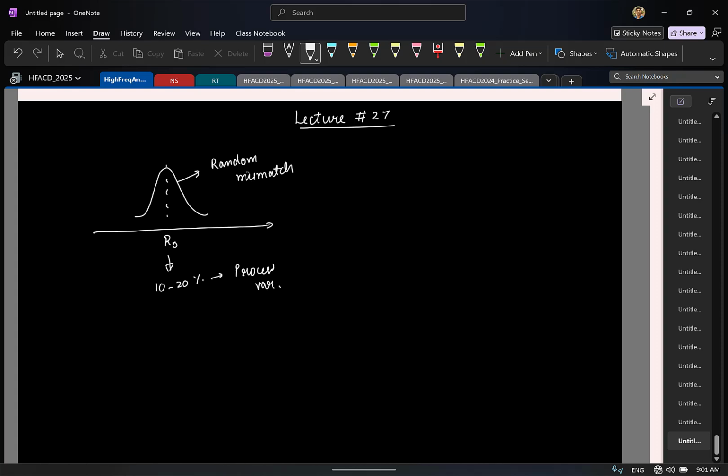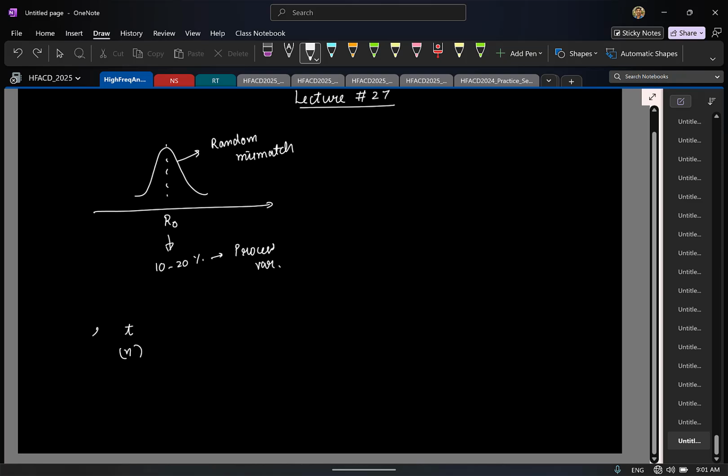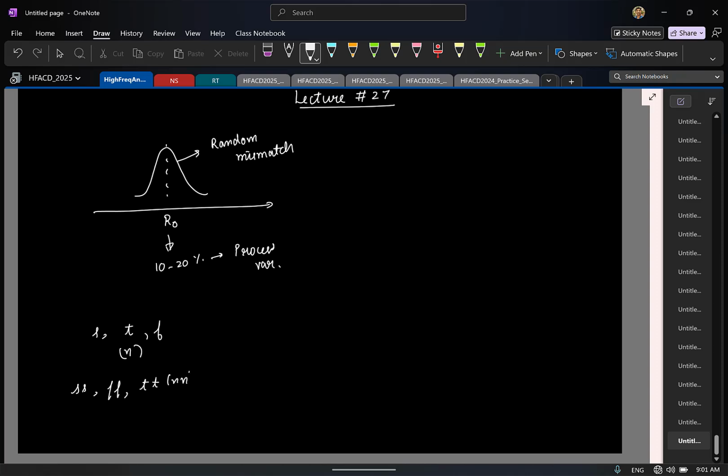Depending on whether the MOSFETs are all coming in with the nominal value, or whether the parameters are such that the MOSFET is slow or fast, we define 3 different corners, and with the combination of NMOS and PMOS we define 5 worst case corners: slow, fast, the typical or the nominal corner, and fast NMOS slow PMOS, or slow NMOS fast PMOS.